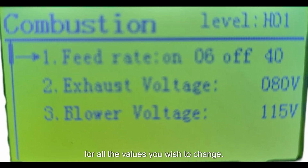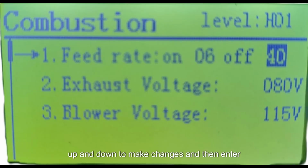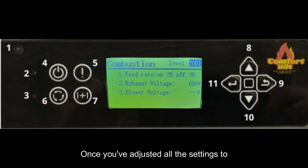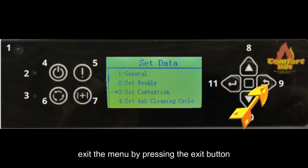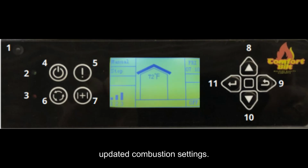For all the values you wish to change, just use this same method of pressing Enter to highlight, up and down to make changes, and then Enter again to lock in your changes. Once you've adjusted all the settings to your preferences or the suggested settings provided by a technician, exit the menu by pressing the Exit button to return to the previous menu. Your stove will now operate with the updated combustion settings.